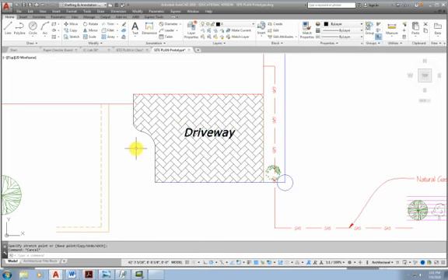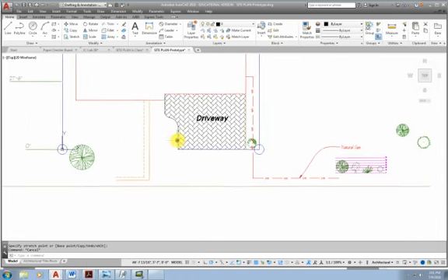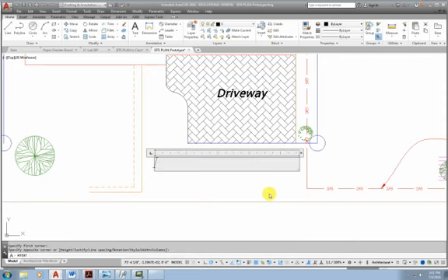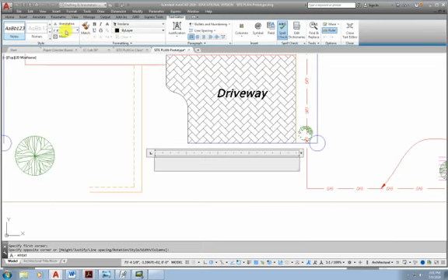And then if we go down to the other text, if we want something a little bit smaller, we can come in here and say multi-line text, and we can put in this box, and then I can bring this down to 1 foot. And you have to remember that the text is scaled according to the dimension scale. So we'll say lot 11, comma, block 7.